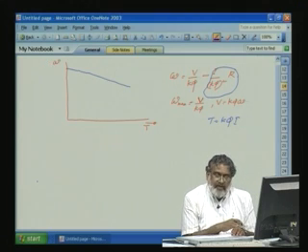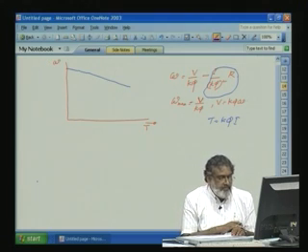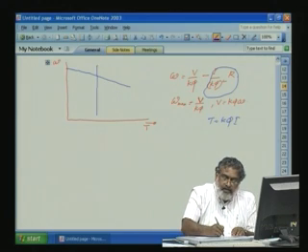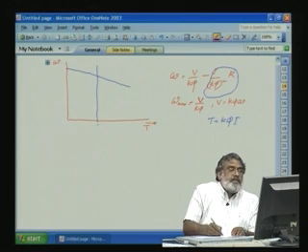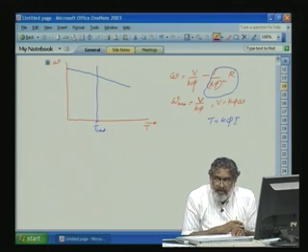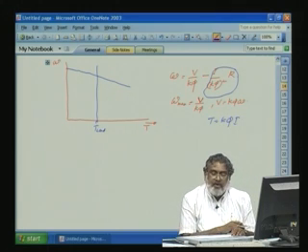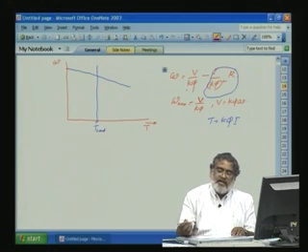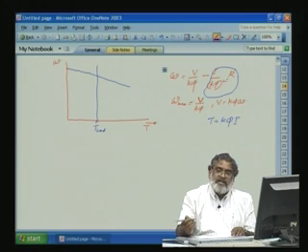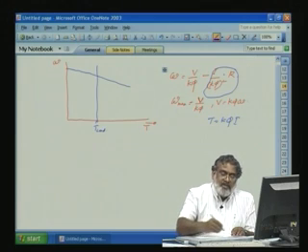Now, if you see here, can we have a speed control of the machine? Let us say torque is fixed, load torque is fixed. This is the load torque what we want. T load. Okay. Now, so I is fixed. Can we have a speed control here? If you see this equation, V is fixed. So, the maximum speed is fixed. Now, how can we have a speed control? Suppose I increase the resistance R. R is the armature resistance. If I increase the R, this drop will become like this.